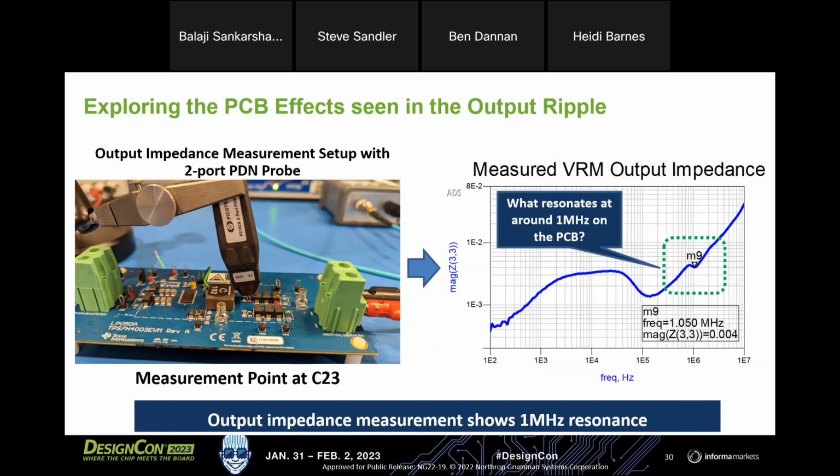Another thing about high power is that it's not so much the power supply that becomes important, but the interconnects do become more obvious. Cables are longer and the cables have higher inductance than they do at low power measurements. And so we need to be much more aware of the impact of the interconnects in the model. And so we need to make sure we get those right also.